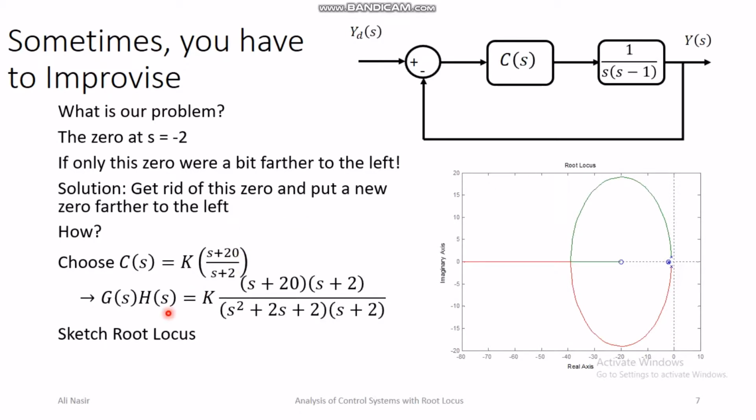So this is a simple phase lag controller, but the real trick was the pole zero cancellation. We were not thinking about the phase lag controller as such, we were thinking about pole zero cancellation, and it turned out that when we did the pole zero cancellation, the controller that we ended up using was the phase lag controller.